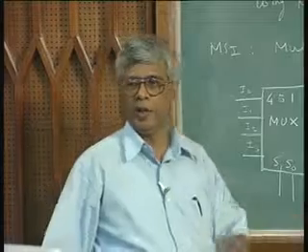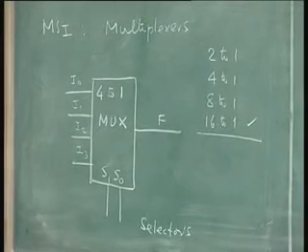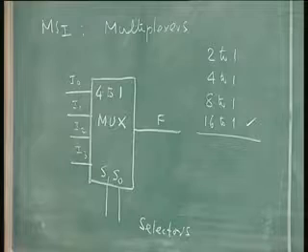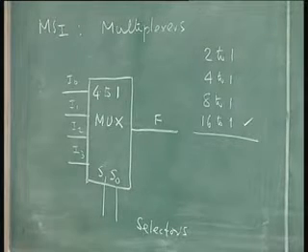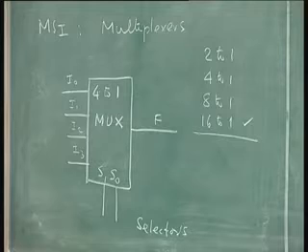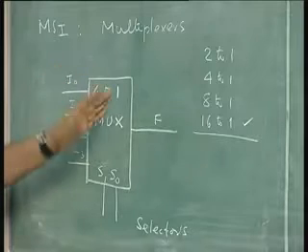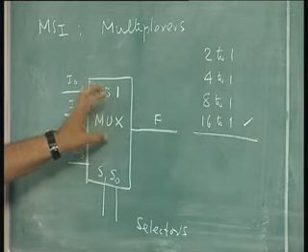But beyond that, you have to make your own muxes. That is possible. Having a smaller mux, you can build a larger mux. You can connect a tree of multiplexers to realize larger muxes.